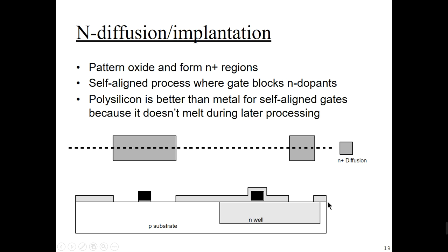And after that, the diffusion process. For the NMOS or PMOS transistor, excluding the gate, we have two more terminals, source and drain. Those two terminals are designed with the help of diffusion. For the NMOS transistor we use N-diffusion, and for the PMOS transistor we use P-diffusion.